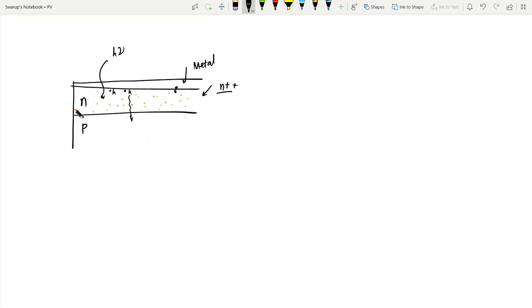Again, if you draw a little more detailed, here we have the barrier width, or let's say this is our active region, the total active region is this one. So the photogenerated holes have to enter into this active region at least. Then we have the built-in electric field, and they will be collected towards the p region, but they have to diffuse and enter, right.